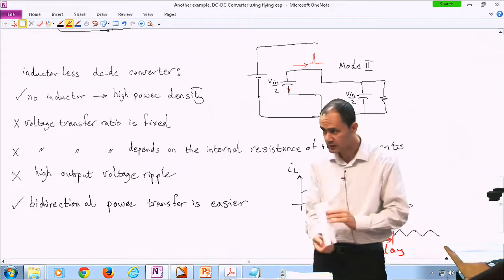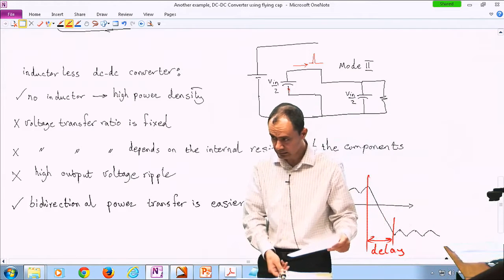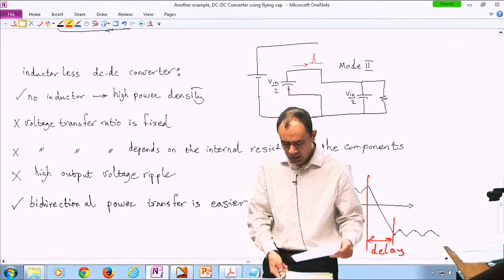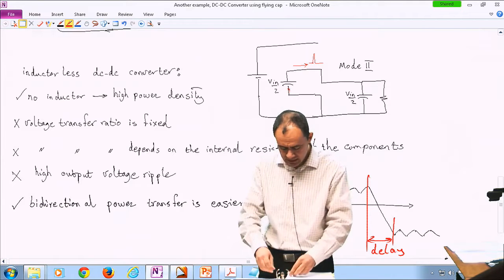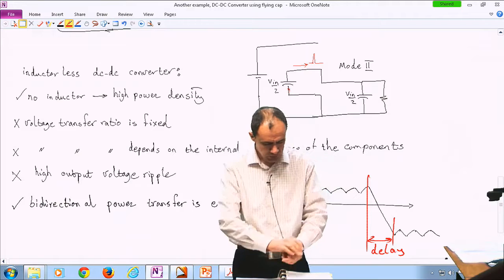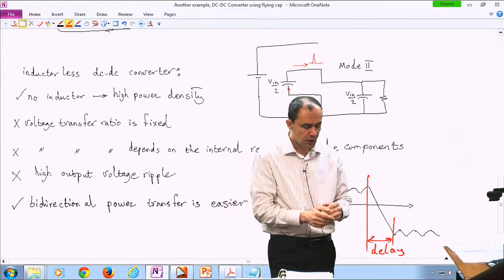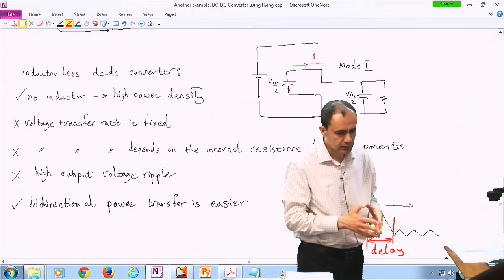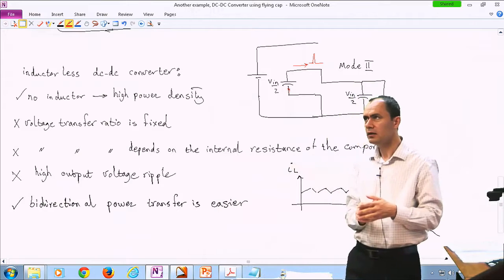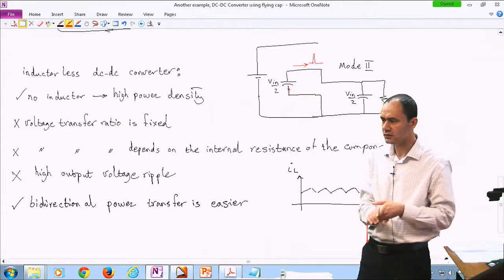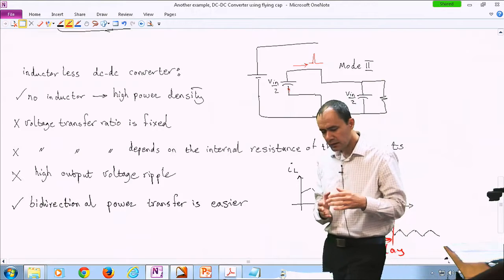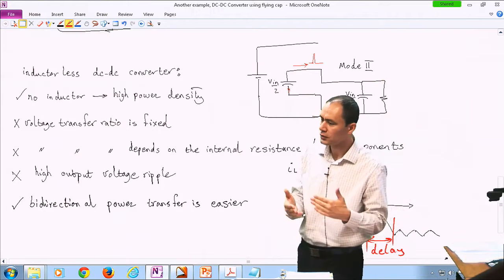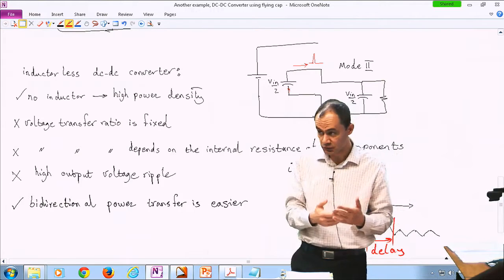Excuse me. Yes. I have a question. Can we eliminate having a compensator for this topology because there is no inductor? The compensation, yes, actually, as a matter of fact, when it comes to controlling this, you don't really need a compensation network. I shouldn't say you don't need a feedback loop, but it naturally gives you an output voltage which is half of the input voltage, ideally.